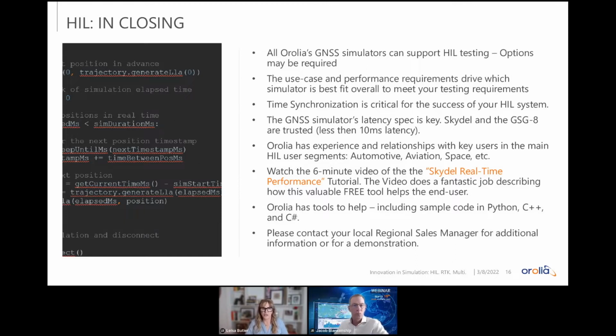Time synchronization is critical for the success of your HIL system. So, keep that in mind. Understanding what latency you need based on your user requirement or your application is very important. And obviously that drives what simulator is the right fit. Please take a look at that 6-minute video. It's really a great tool for seeing how that performance tool works.